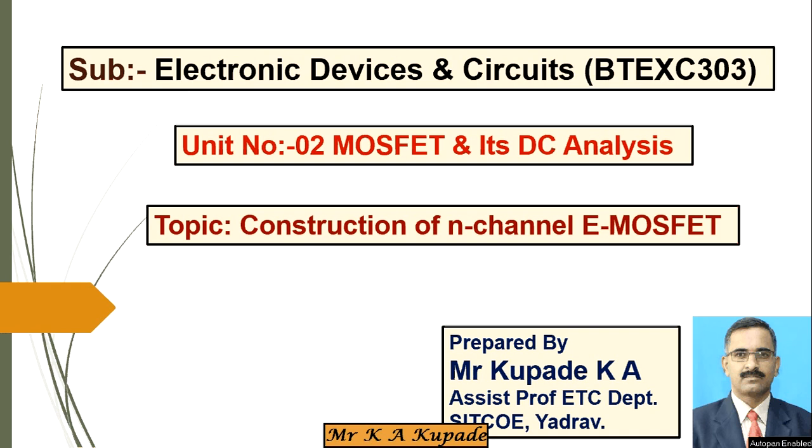Don't confuse this: the channel is not the entire region in the MOSFET. No, that is not the case. Here, a very lightly doped substrate material is considered, a very slightly conductive or almost non-conductive type of substrate material, and on that, the insulating silicon dioxide is diffused, which acts as a type of glass.